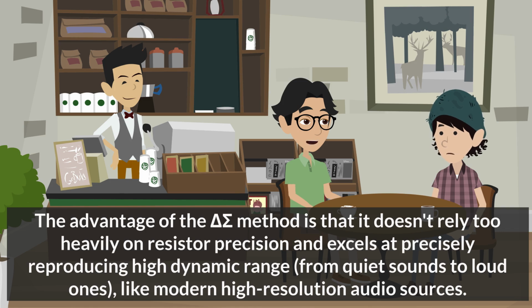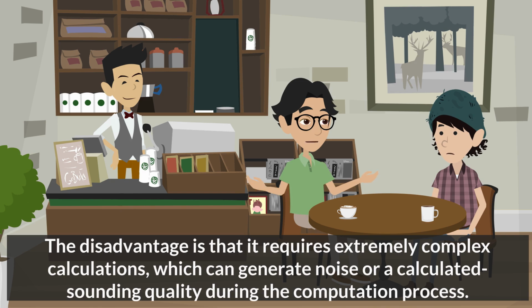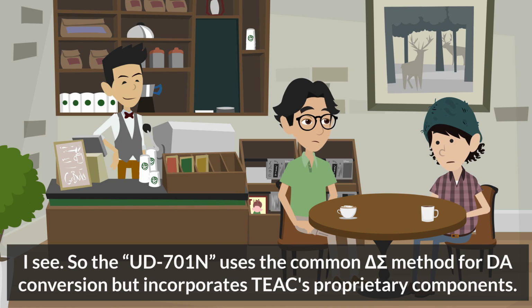The advantage of the delta sigma method is that it doesn't rely too heavily on resistor precision and excels at precisely reproducing high dynamic range, from quiet sounds to loud ones, like modern high-resolution audio sources. The disadvantage is that it requires extremely complex calculations, which can generate noise or a calculated sounding quality during the computation process. I see. So the UD-701N uses the common delta sigma method for DA conversion but incorporates TEAC's proprietary